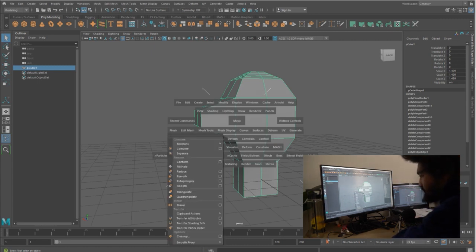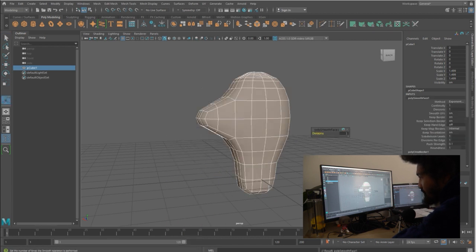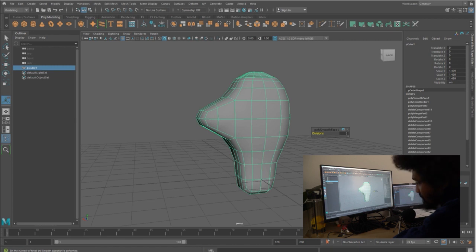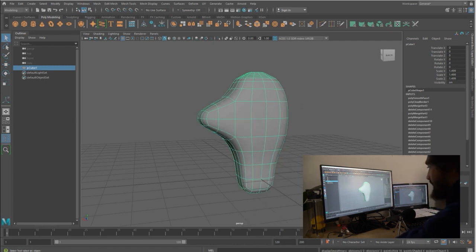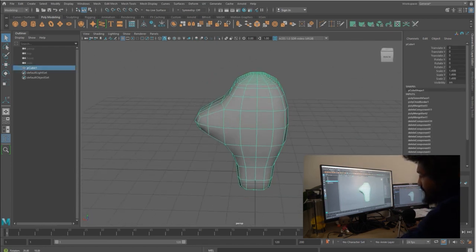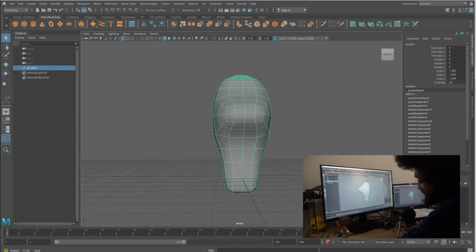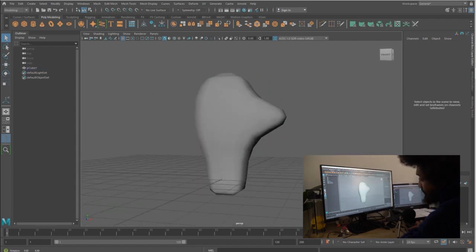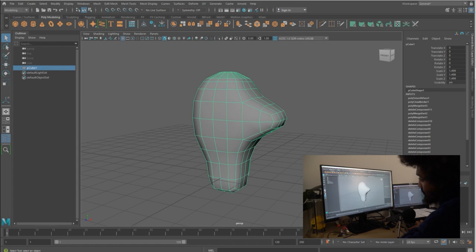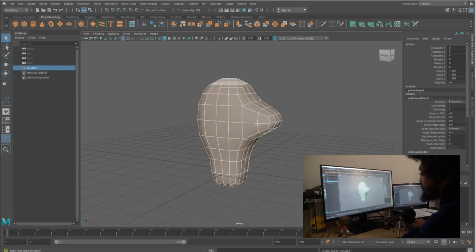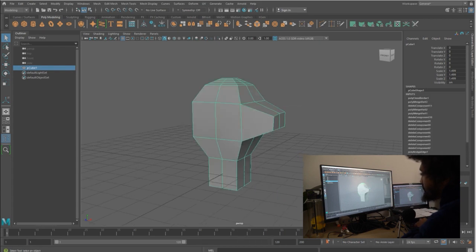So you can smooth the mesh as well. What happens with smooth is it's gonna create one subdivision for each polygon. Basically now you can see everything is twice as heavy in terms of faces, and you're gonna round all the geo because there is more connection from one face to another, so it's less sharp. Okay, so that's for the basic tools on the mesh. I'm just doing Control Z.